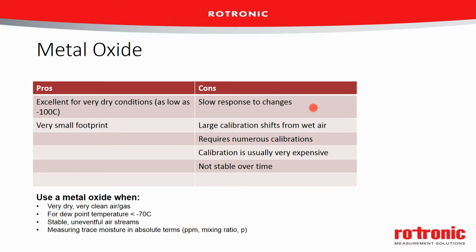We'd bring in the aluminum oxide hygrometer, and we would let that stabilize for 24 hours before we could come back and actually get a reliable reading on the dew point. Now, I'm not saying they all take 24 hours, just saying they do tend to respond slowly to changes. If they get wet, they're done. They have to be recalibrated. They do require a lot of maintenance, frequent calibrations, because they're not very stable over time.